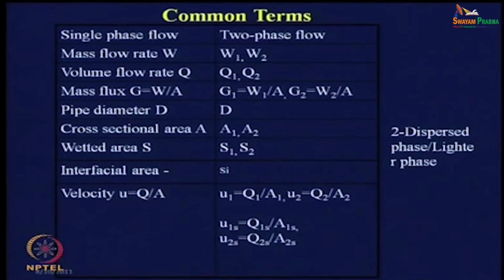So, it is usually the volume or the fraction of the total volume occupied by the heavier phase. Therefore, usually what we do for this particular case is we specify it as HL. And we define HL as, now remember one thing, this HL or this alpha may not be constant throughout the entire channel. It may not even remain constant with time as well. There can be fluctuations with time, and there can be fluctuations with distance as well.